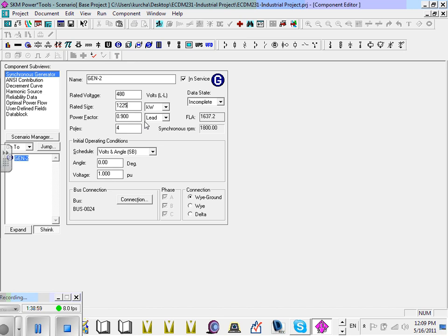1225 kW, something similar to this. You guys are going to see your generator. You can adjust it at any time. I put 1225 and change it to kW. Okay, and the voltage is okay. Everything is okay. Don't miss. Is your voltage 480? If it's different than 480, make sure you change it. Change it to 1225 kW and exit.